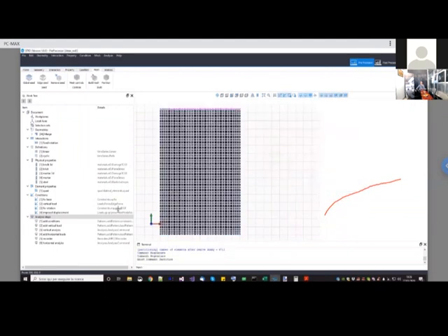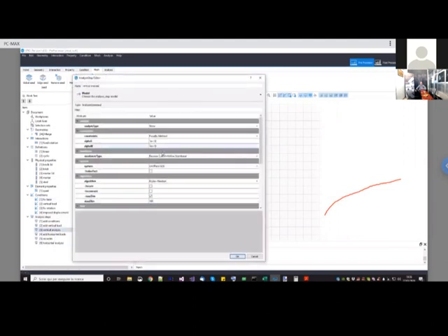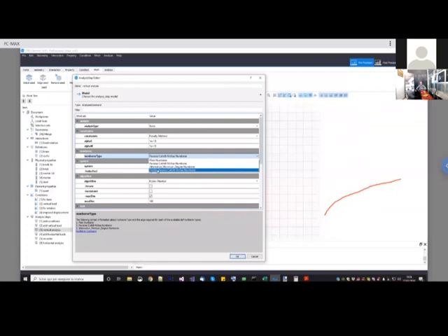Now, when you have partitioned your mesh, you just need to do very few changes to make the analysis run in parallel. Basically, in the analysis, you should do 2 changes. The first one should be the numberer. The numberer should be the parallel one. There is only one, so you cannot make any error here. Just choose the parallel RCM.